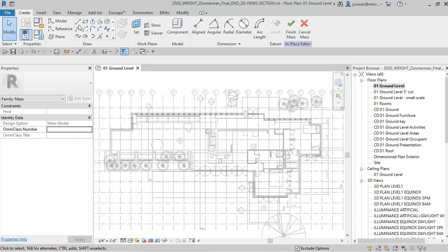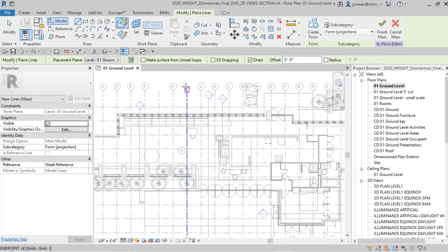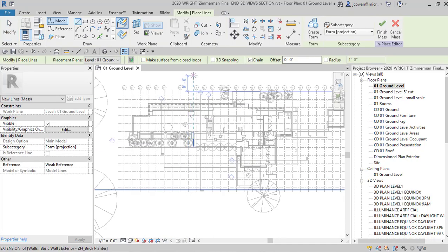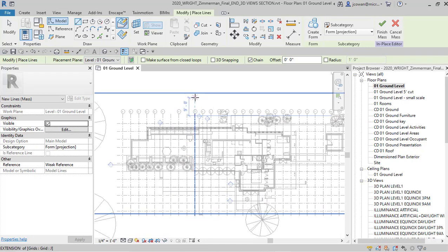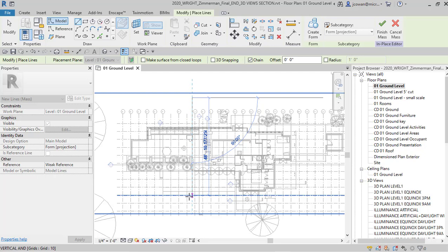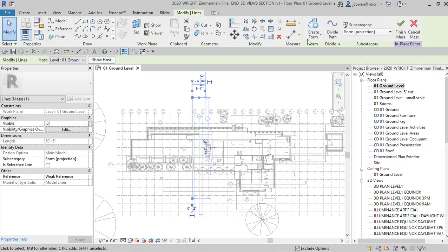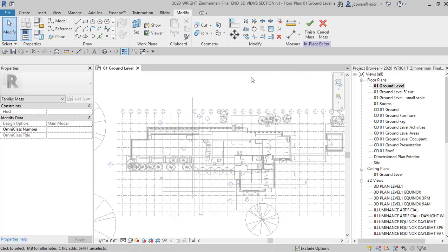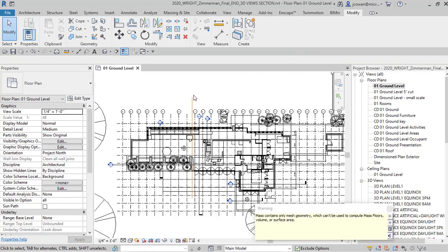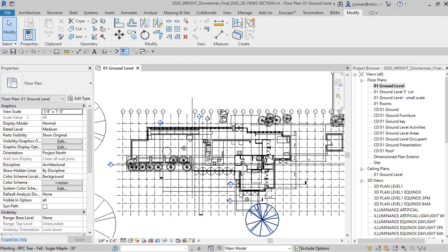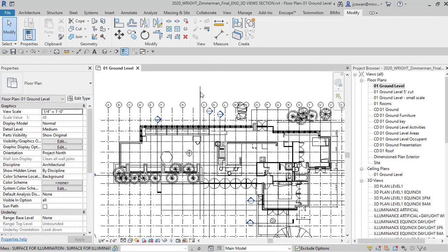And I'll just draw a line that would be representative of the plane that I want, when it's extruded, the plane that I want to have through my model. So I'm just drawing it through here. Escape, then pick it. Pick the line and say create a 3D form, solid form. It's going to extrude that up, and then I can say I'm finished. Right. The message from Revit is just that there's no volume, it's only a surface.